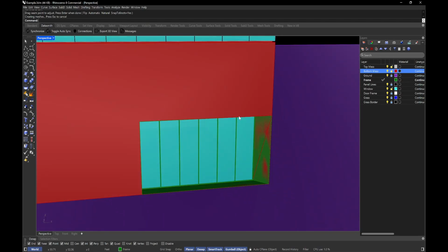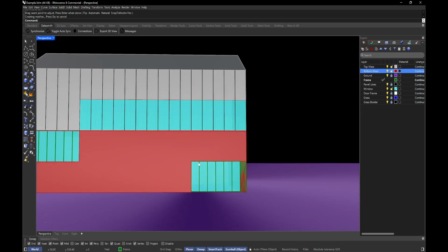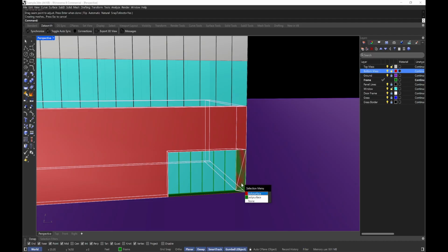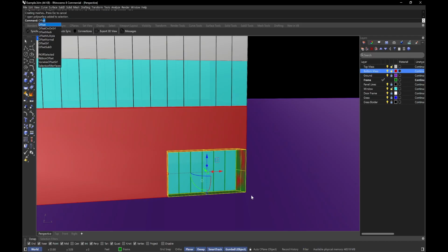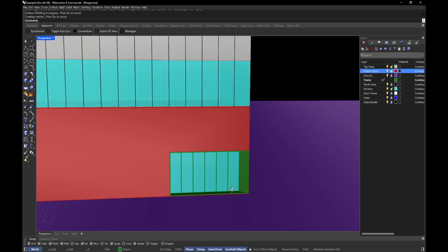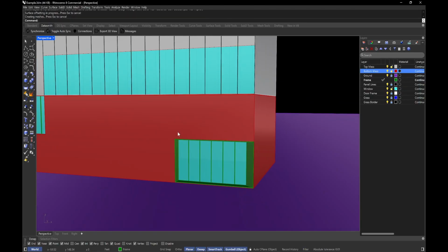And I want this to be like maybe like a nice wood accent. Because again, I'm gonna make this either like stone or brick or concrete. I'll see once we get to Twinmotion, I'll see. So I'm gonna take this one and I'm gonna offset surface. Let me just flip it because I want it to go in and I'll do like 2 inches. There you go, like that. So there's like this nice accent, you know?